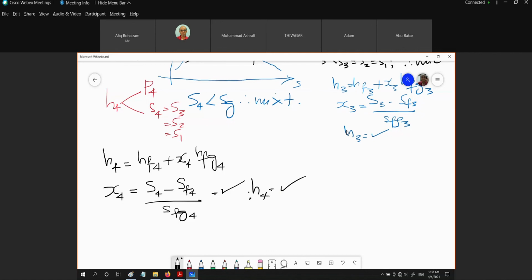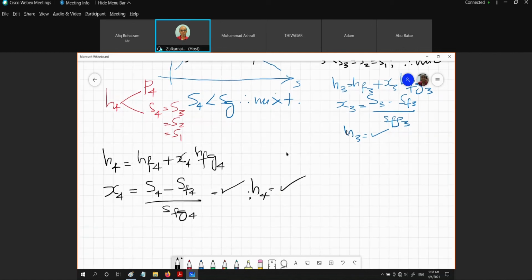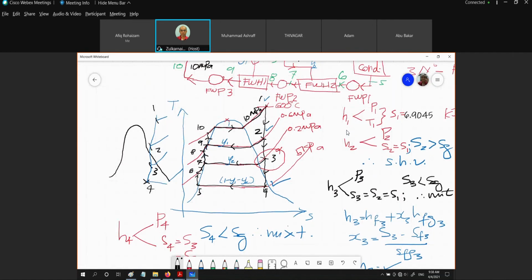Okay. Then again, you get your H4, H3. H2 is based on P2, S2. Then you get your H5. What is H5? H5 is HF at 5 kPa. What is H7? H7 is equal to HF at 0.2 megapascal.